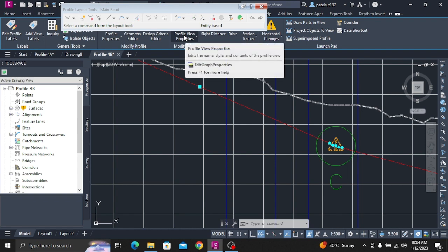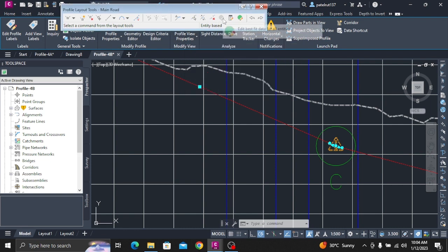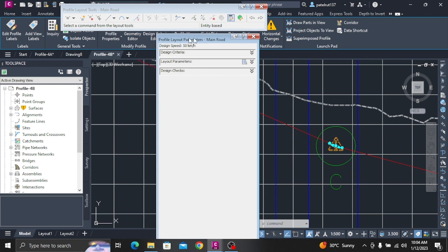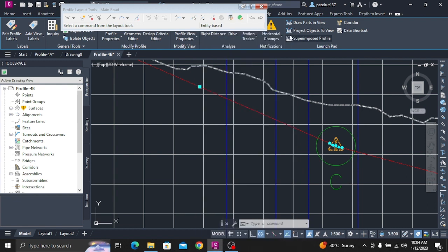Zoom out so you can see both profile views. When you applied the Major Grid style, which includes grid padding above and below the profile, PV, 1, enlarged to overlap PV, 2. Click PV, 2, and move it up above the title block for PV, 1. Click the PV, 1, grid to select the profile view. Right-click. Click Edit Profile View Style. In the Profile View Style dialog box, on the Grid tab, under Grid Padding, change the padding of all 4 axes to 1.0000.